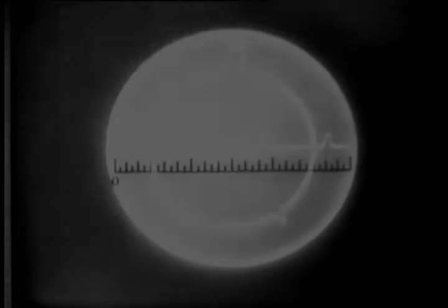This is 0 range. The returning target echo voltage is also applied to the deflecting rod, and another smaller pip will be formed somewhere on the circumference of the circle. As you can see, this scope gives us everything an A-scope did: a main bang, a target pip, and a baseline along which you measure range.